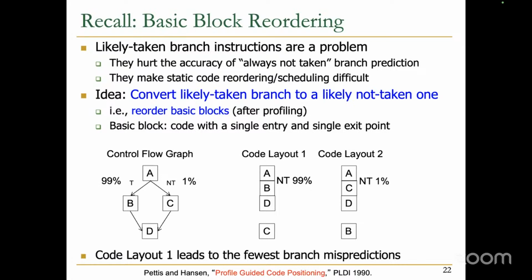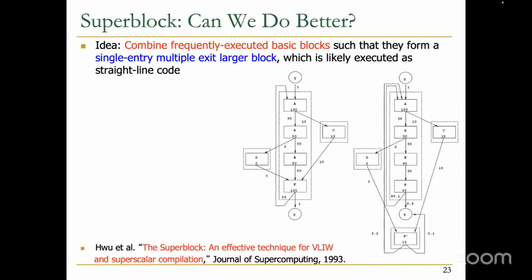It's kind of similar to that, right? Except in this case, we're relying on branch prediction. So if the branch is executed such that you mispredicted, you flush the pipeline. Here, instead of flushing the pipeline, you're relying on the compiler. If you actually go out, you do some other stuff to undo what you shouldn't have done.